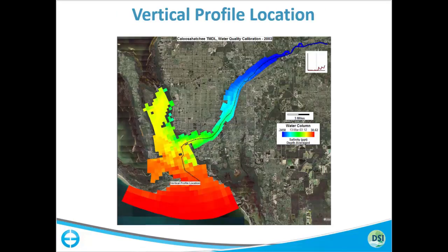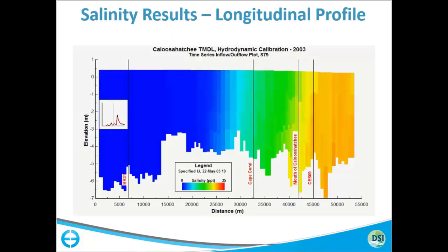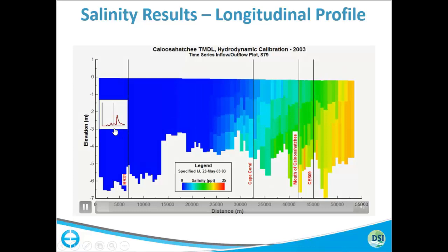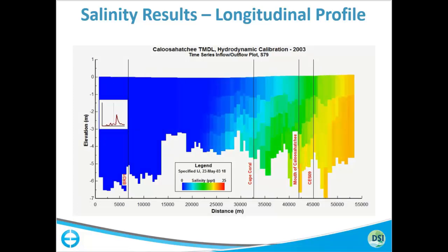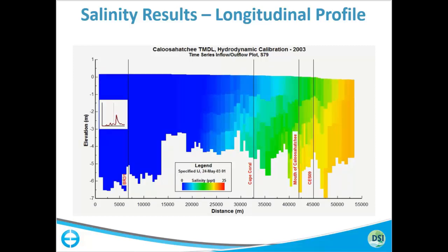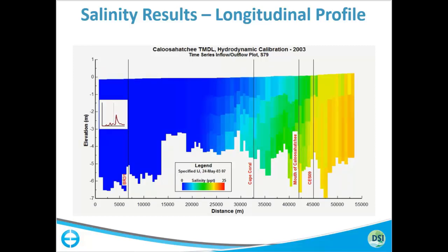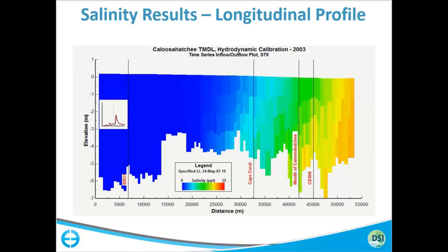So now we'll create another animation for this center line. We want to create from this point to upstream headwaters. So you can use EE to create a polyline. What it does is take out all the concentrations for those cells and then create a nice layout. So here this is the upstream, this is your downstream at the Gulf, and you can see the concentrations varying at different layers. This kind of nice gradient is because you have a stratification at the particular layer.